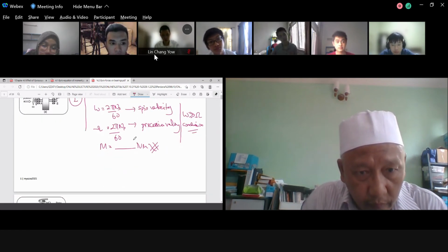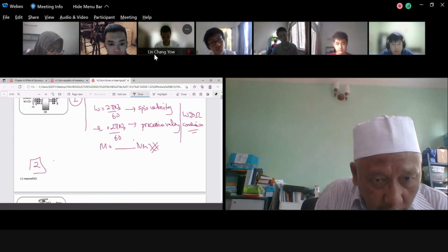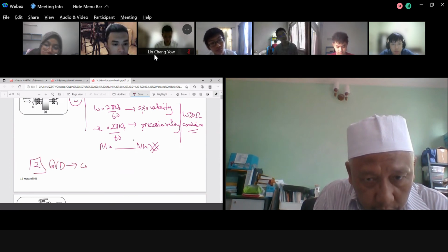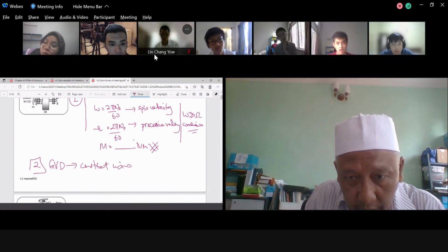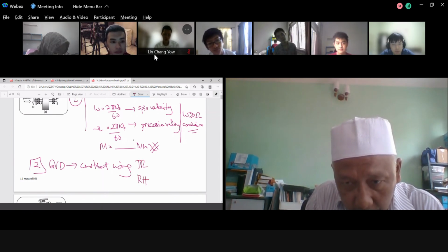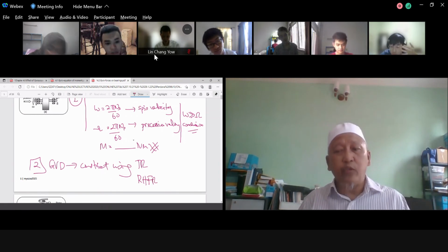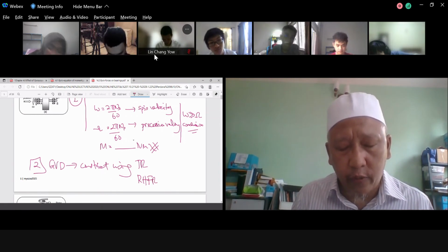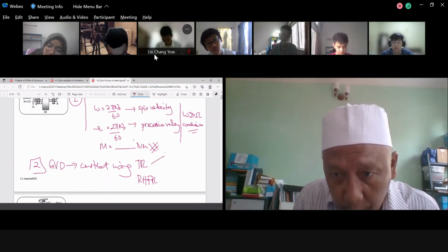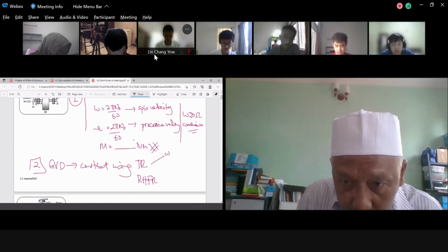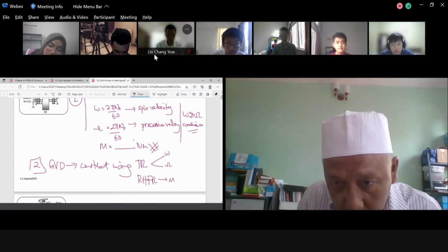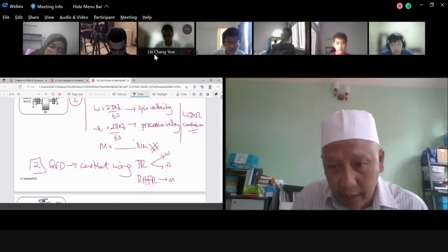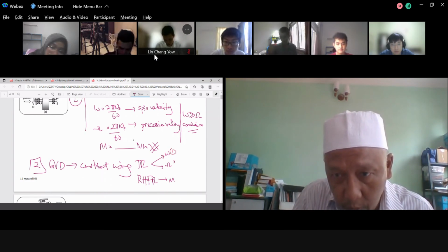Number two is to construct the gyroscopic vector diagram. This one we construct using, as I mentioned earlier, the thumb rule and the right hand Fleming rule. So you keep asking which one I would like to start first. Use the thumb rule: start with the omega or spin, then the precession, and this one will tell you the moment. Number one, number two, number three.